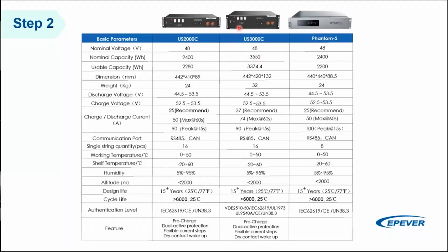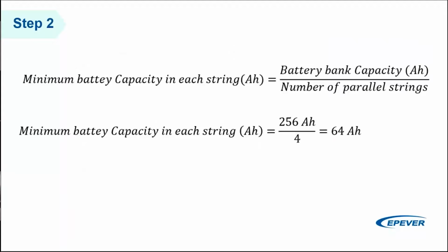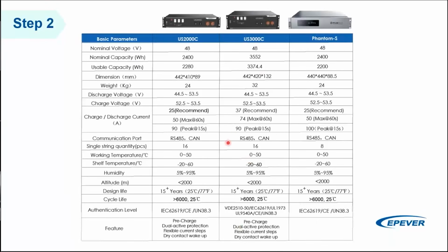Well, why these kind of batteries? Because of the simplicity and the modularity of these batteries, which, as you can see, is 3.5 kilowatt hours. So if I have 4 of them, I'm meeting the criteria that I mentioned here. I'm sure that this battery is capable of providing the power that I need. And this capacity here makes it suitable for small and large accumulation systems.